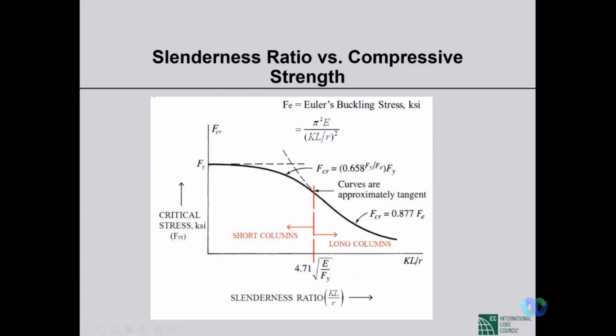There will be elastic buckling, long before the stress reaches yield stress, the member will buckle. This is member buckling, not local buckling. The whole member will buckle. So due to compression, if the slenderness ratio is high, then we'll find buckling first. Then the capacity will be governed by buckling.